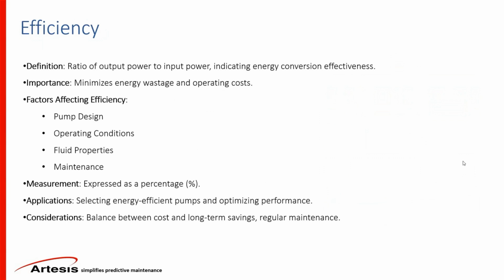So you have an electric motor, in this case, that powers the pump, and how much of that power will be converted to an effective use of the incoming power. This reflects the pump's ability to minimize energy waste and operation cost. Of course, higher efficiency would lead to reduced energy consumption and environmental impact. This is typically measured in terms of percentage, and you would have the efficiency charts of the pump provided by the manufacturer, which we are going to look at shortly.